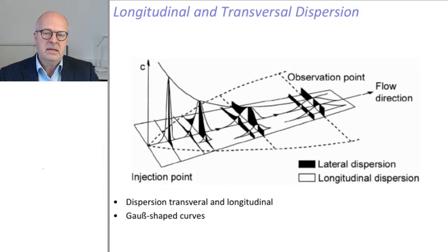Now, if we take a sample at a certain point, so if we stand by the river at a certain location, we take samples, or we even have an instrument to measure the concentration live, we will see that the shape is not bell-shaped anymore, that it's asymmetric. The explanation for this phenomenon is easy. You can actually observe dispersion taking place.